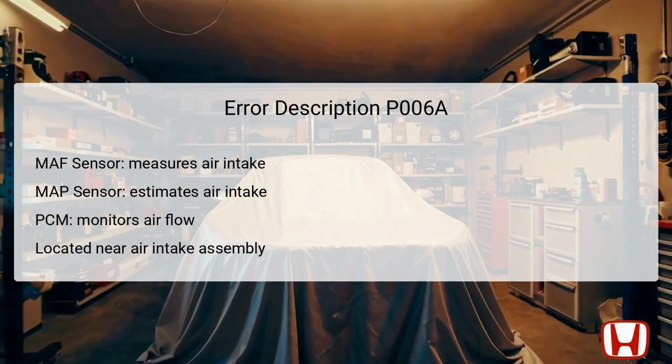This malfunction relates specifically to the area around the air intake assembly, where both sensors are housed. Therefore, if there's a significant difference in the readings from these two sensors, the PCM identifies this as a potential issue indicated by the DTC P006A coding. It is crucial to diagnose and address any issues with these components to ensure proper engine function.